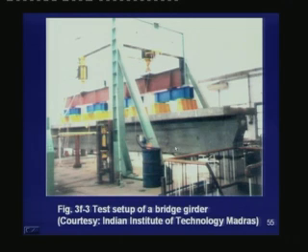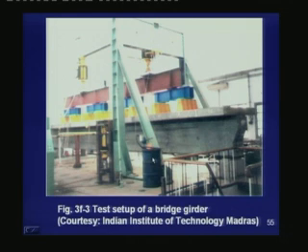Now, in this test, we are simulating the distributed load by a series of point loads, which is more applicable for a bridge structure. And here we see on the right hand side, the anchorage block has been grouted. The section is a flange section, where the flange width is constant throughout the length, but the width of the web has been increased near the ends so as to have less stress concentration at the ends and so as to fix the tendons properly. This is a beam which has been tested to failure to calculate its ultimate moment capacity.